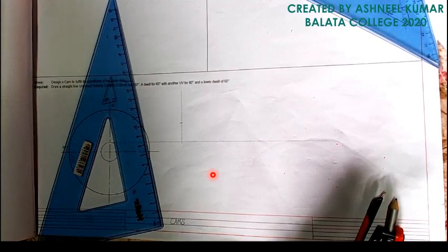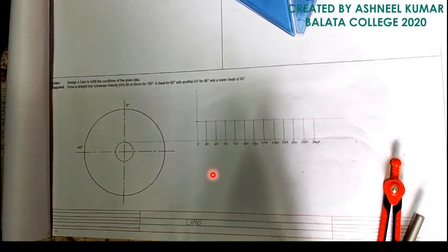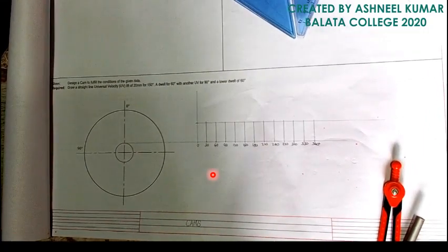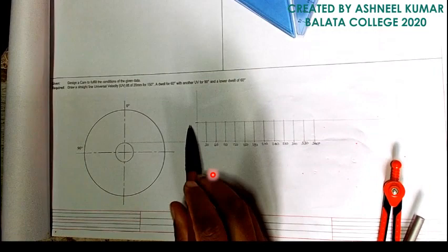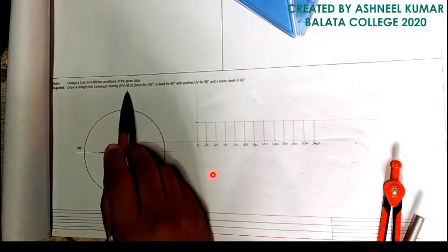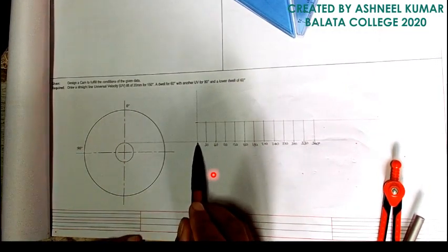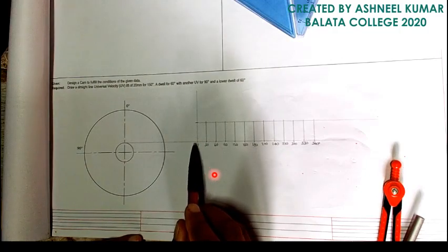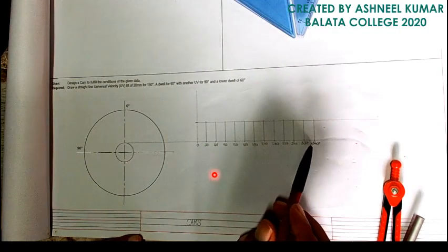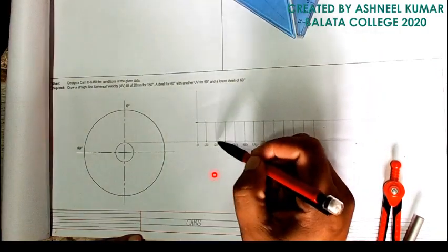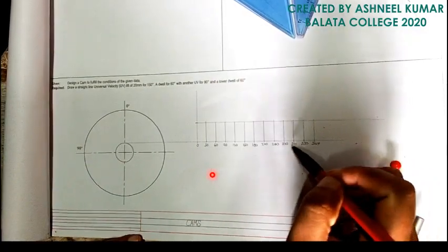Right, you'll mark it 12 times here. That's the height of 20. From there, you'll make a rectangle, and all the divisions here, you're going to take it straight up, and you're going to label it 0, 30, 60, 90. Those are the angles. So each division there represents 30 degrees.